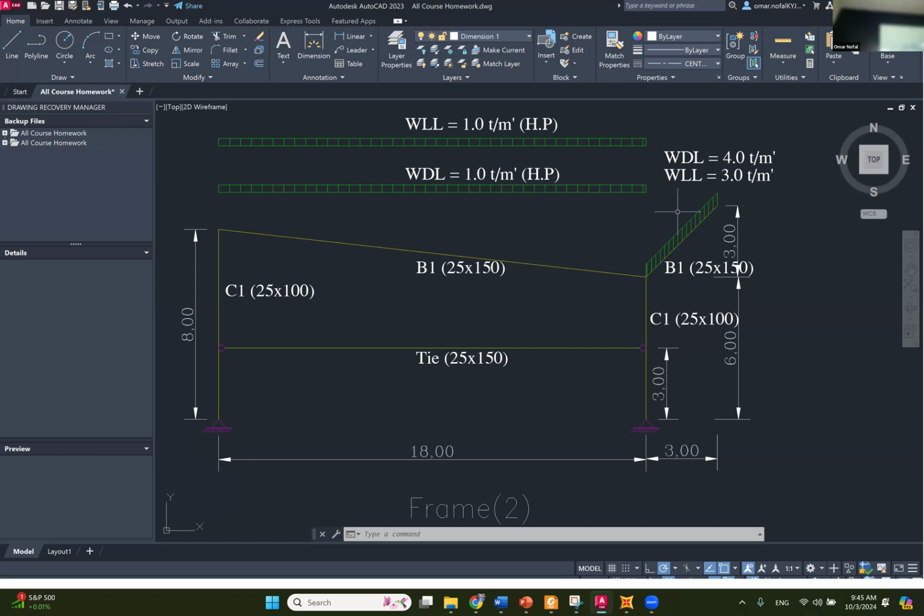Also, it's gonna have a bending moment because of its own weight. But if we neglect its own weight with respect to the total load on the structure, it's gonna be a tie, right? Okay, so right now, when I model this system, I'm gonna model every beam and everything. If I give you this problem in the exam to solve it for structure analysis, you are not gonna assume the own weight of the structure, right? You are gonna use this load to develop the bending moment. Because I didn't give you the gamma of the concrete and I didn't give you anything. But I'm giving you these cross sections just to model the stiffness of the structure.